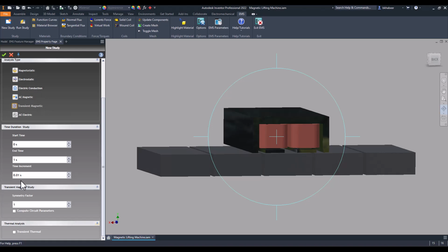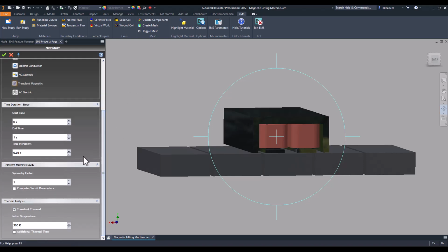In addition to these electromagnetic solvers, we offer the possibility to couple these modules or analyses to thermal simulation. So you can compute the heat generated because of ohmic losses. For example, here we have a DC current applied to the coils, so we get ohmic losses and some heat generated in these coils. So the software can help you get the steady state or the transient temperature. So you can get the final steady state temperature, or you can see a variation of the temperature versus time through this coupling.